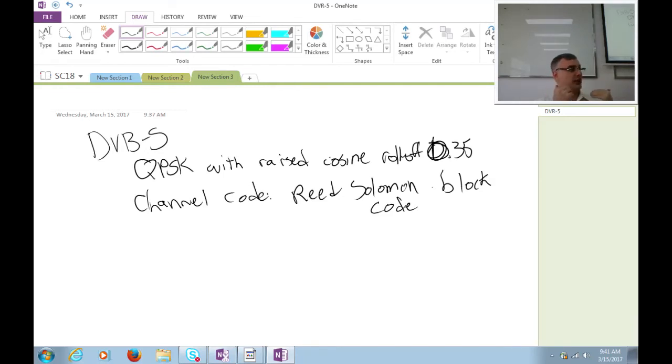Forward error correction is a little bit different, though, because in this instance, not only are we adding bits to detect errors, but if we add them in the right way and enough of them, then it gives us the ability to correct the error. And that's really how you make the most of what could be potentially a lossy communication system to transmit a virtually error-free signal. We never say exactly error-free because you would need infinite complexity to achieve that. But once you get down to bit error rates of 10 to the minus 7th, for example, that's considered virtually error-free.